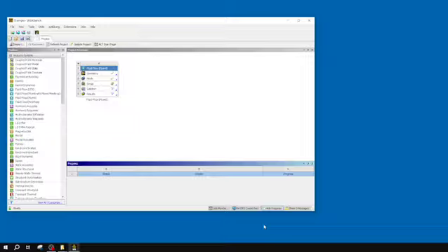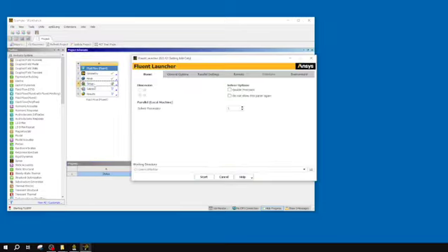Alright, so now that that has finished meshing, you can see it's moved to a check and my setup gets this little circular arrow thing. So I'm going to double click on my setup. Because we selected our Fluent fluid flow model, it's going to ask me how I want to set up my Fluent launcher. I'm going to want this to be double precision, and I believe I'm going to run this at, let's go 6 cores. Let me actually double check that.